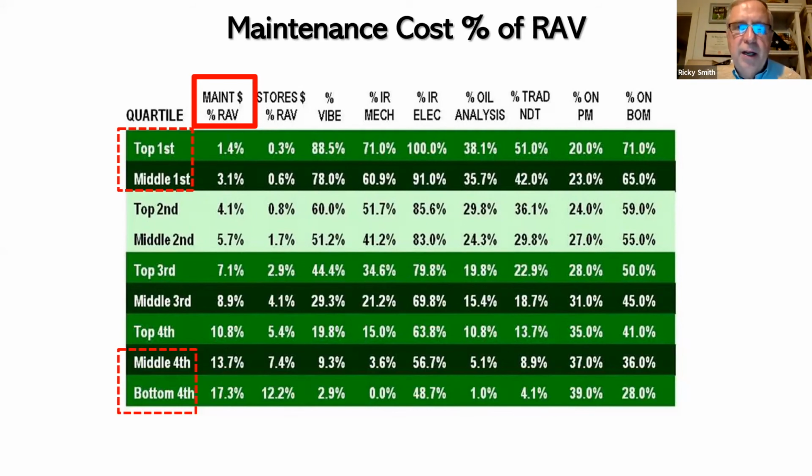Are there any different KPIs that we're using for predictive compared with proactive strategy? It's the work. I mean, if we look at the work that comes from PM and PdM, more work should come from predictive maintenance and preventive maintenance. Preventive maintenance is to prevent failure, but the predictive maintenance should be identifying defects far enough in advance so we can plan it and schedule it before it impacts production.